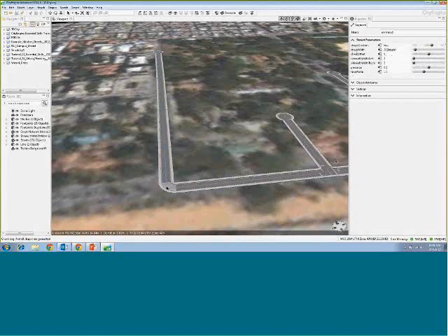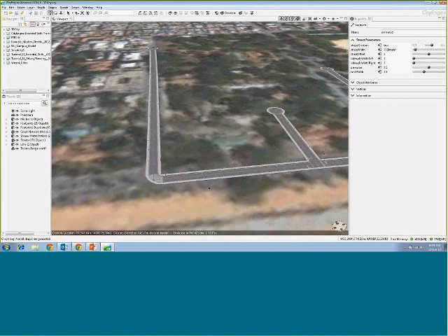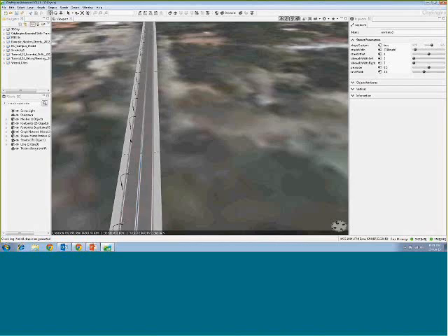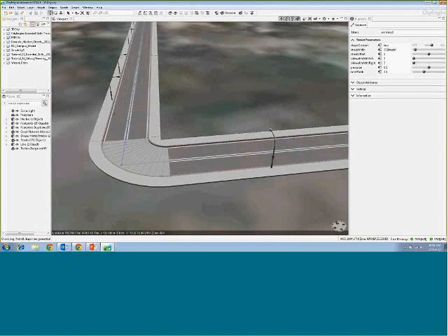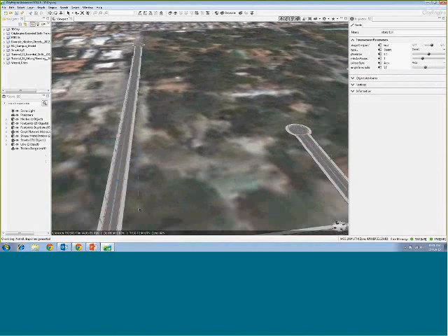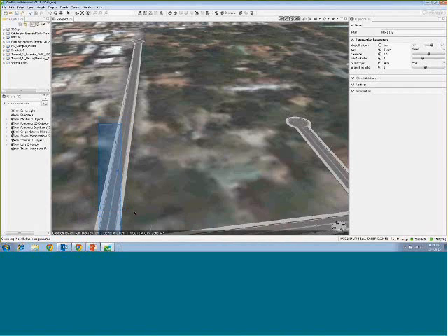Now every road would also have attributes along with it. You may want to change a few. Selecting any of the junctions, we get a detailed attribute about everything. You may make use of these particular rules shared through modern street examples. You just have to go to Esri.com CityEngine and you may get these templates and examples. You may make use of modern street examples to model your streets.